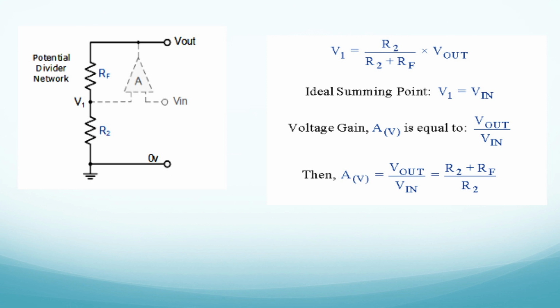If you want a gain greater than 1, you have to go with only the non-inverting amplifier. And the inference we draw from the inverting amplifier and the non-inverting amplifier is that whatever input you give the inverting amplifier, it gives an output with a 180 degree phase shift. Now in the non-inverting amplifier, if you give an input of Vin, you get the same output.